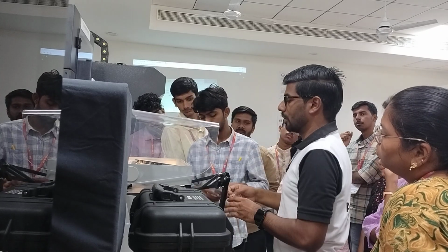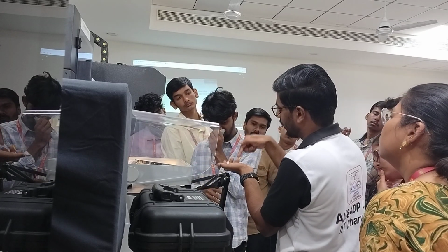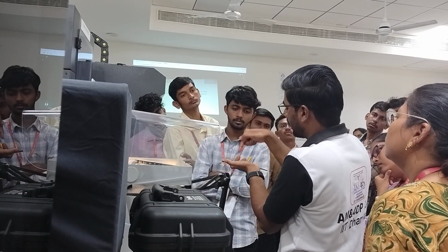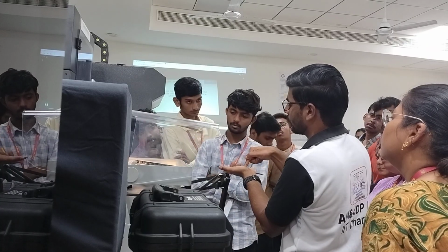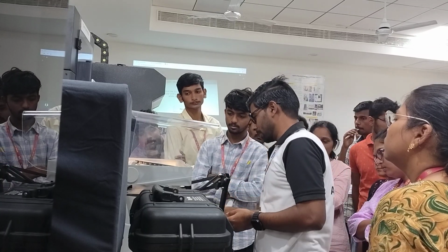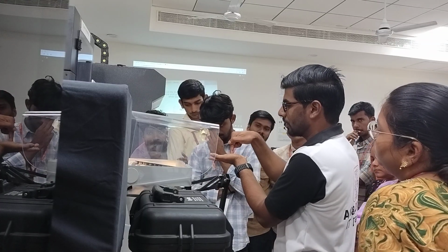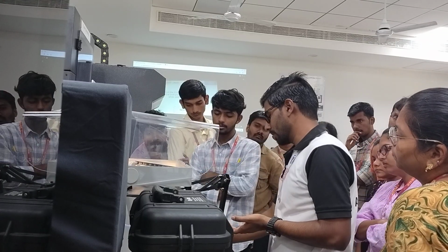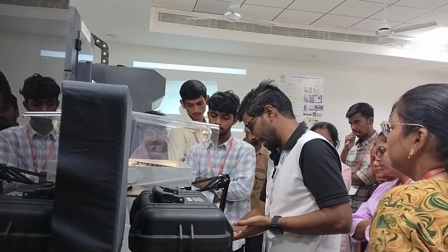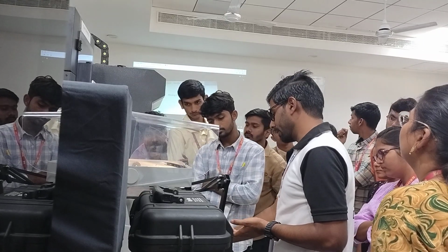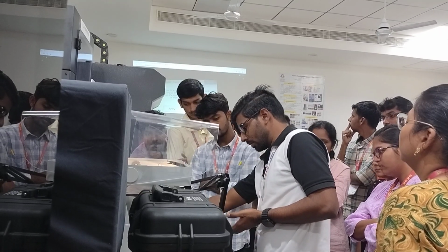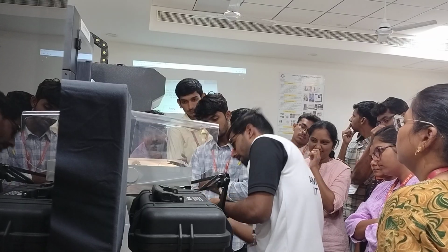This is required because when the deposition is happening, it must not deposit in the air, neither must the nozzle go and strike the bed. So now we know that there is a proper clearance between the bed as well as the nozzles, and the bed is also aligned. I'll click on next. It's moving back to the right position. Oh, this one is again telling me to do the same thing.